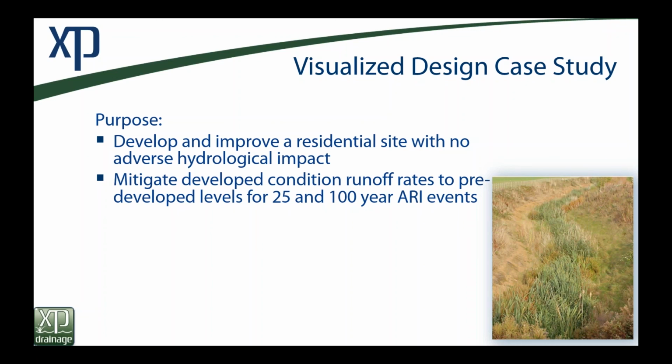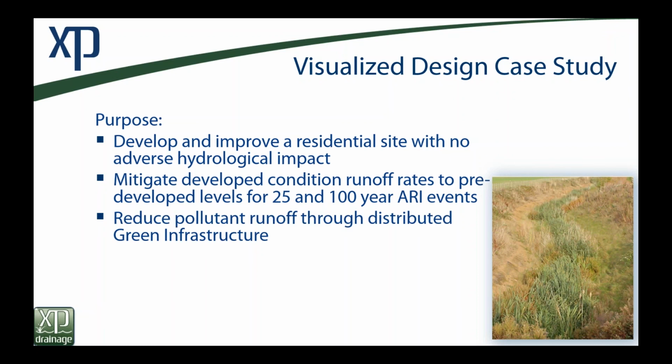And a lot of people could probably argue that that might need to be increased with the rain over the last decade down there. So we're looking at mitigating the discharge from our site in these higher flooding events, as well as treating that water quality storm event.